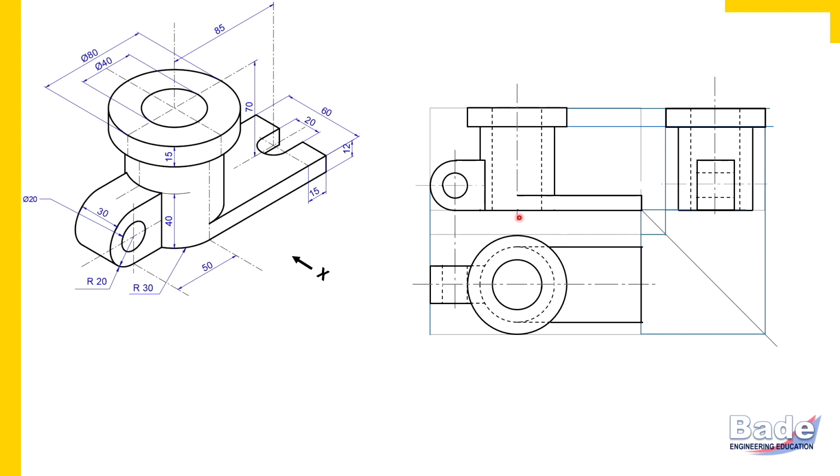And there is one notation used in engineering drawing to indicate a tangential joint on a curved surface, and we are using that notation. Watch here. This small curve at the end of the surface suggests that this strip-like surface merges into the cylindrical surface tangentially. So this is how the top view and front view of the plate are complete.